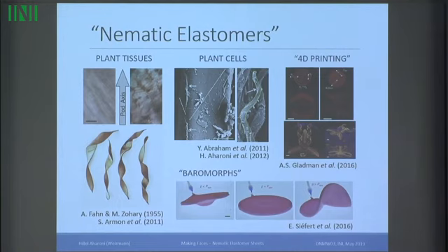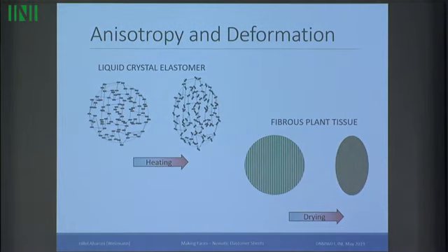Now in all of these examples and in nematic elastomers, the actual nematic elastomers, you have a material that at every point has a direction embedded into it. So this is the nematic director. It's not a polar direction, it's a line direction. And this is, as I said, coupled to the deformation, mechanical deformation or strain of the material.